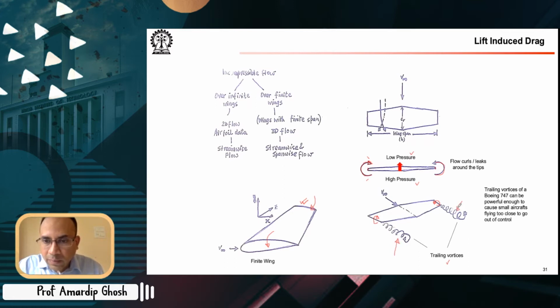We saw a wind tunnel experiment picture in the last lecture. So these vortices can be rendered visible using smoke, and sometimes in real applications, because the pressure becomes very low in the core of these vortices, you can see that you have condensation, which renders these vortices visible. Okay, so sometimes you do not need smoke. The condensation actually allows these vortices to be visualized.